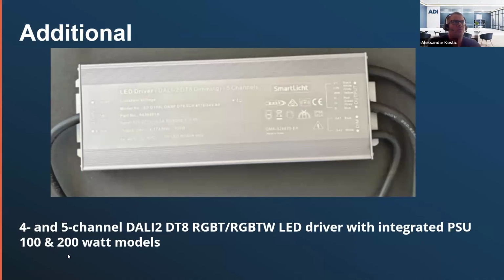Also, what is quite a specific product we have available on this DALI 8 is the 4 and 5 channel LED driver, which has an integrated power supply. We have models with 100 and 200 watts supported. So you have a two-in-one: DALI ballast and power supply. It is typically used with RGB tapes with fixed or tunable white, as they require 4 or 5 channels to fully control the LED tape itself.